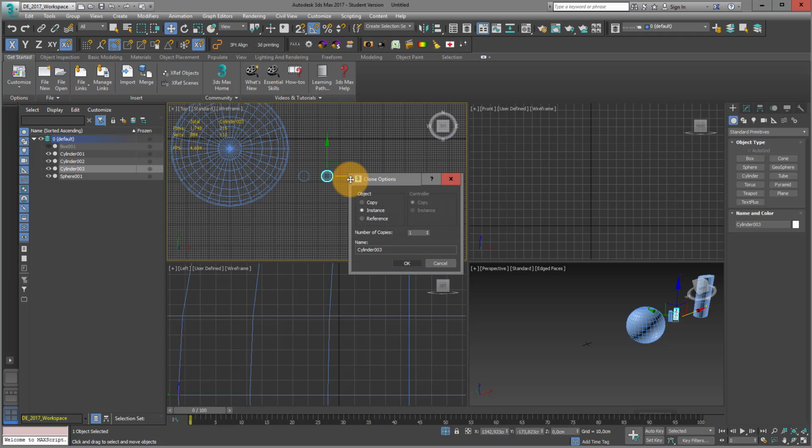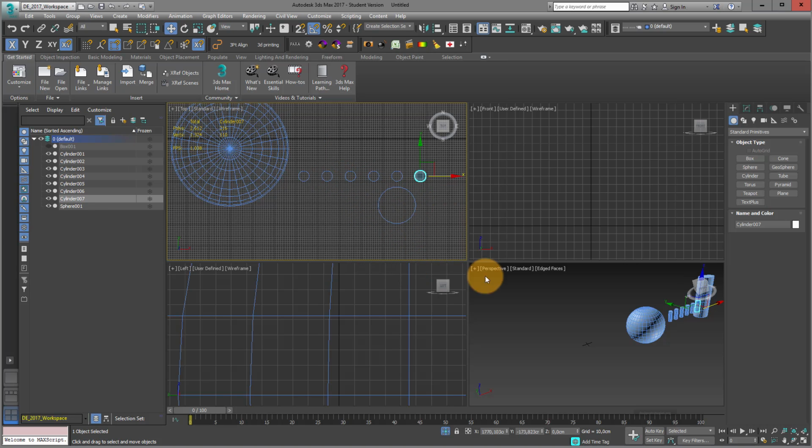And this is the way of how to make copies. We talk about cloning also a little bit later, but I just want to make a copy of 5 objects. Number of copies 5. I finish with OK. And that's a way of how to draw 5 cylinders.